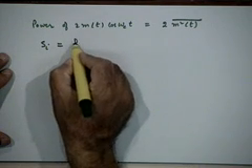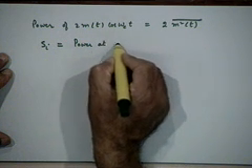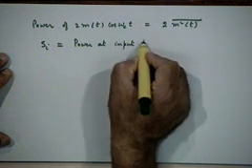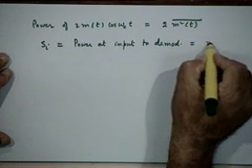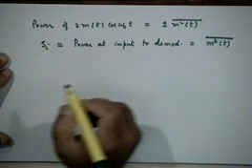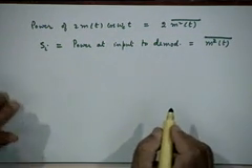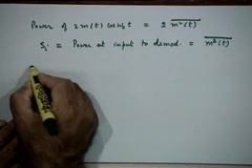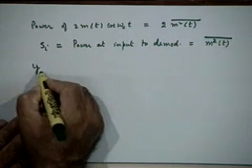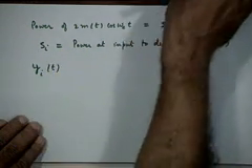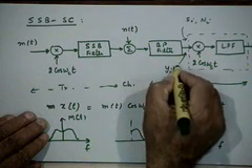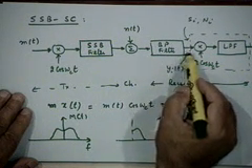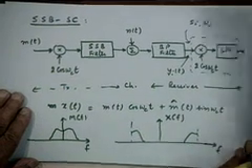So therefore we can say that S sub I, the power at the input to the receiver, input to demodulator I should say, not to receiver, is equal to m square t bar. Simply call it m square bar. So at the demodulator input you have, if I call this signal at the demodulator input as YIT, can we write an expression for this signal YIT?